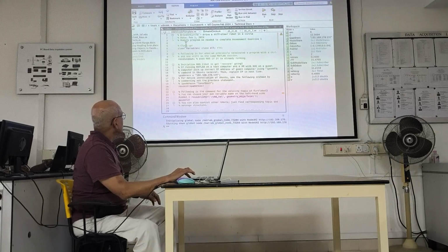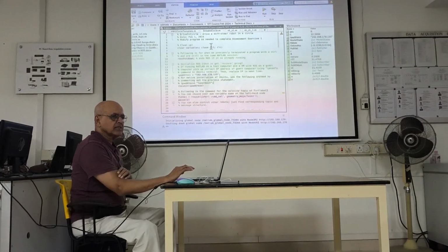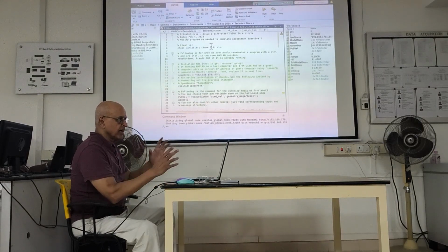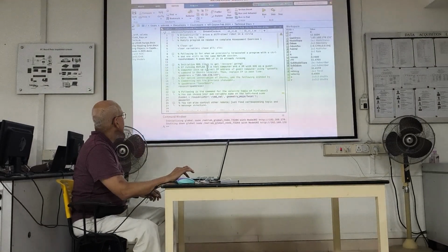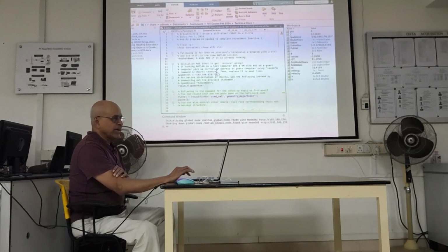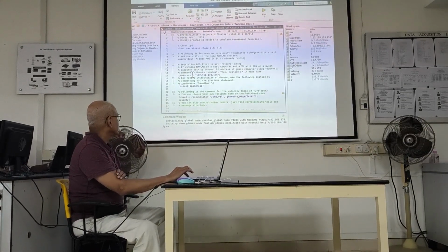But essentially, we clean up the MATLAB environment. I told you why we need to do that, or else the program before and the program that you're running now will all get mixed up in terms of the variables. And then we initialize ROS core. You have to get the IP address if you have a dynamic IP and start ROS core. So that's all standard stuff.